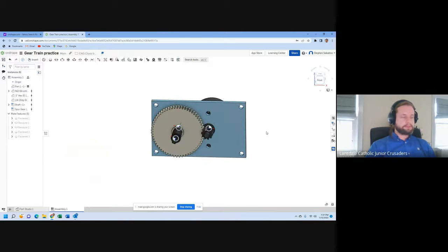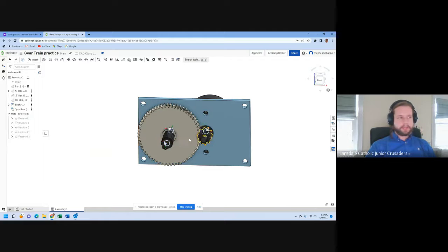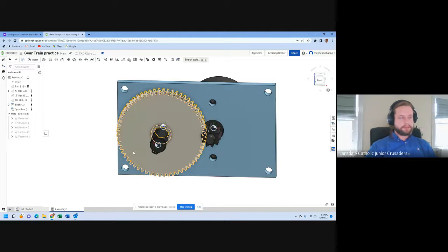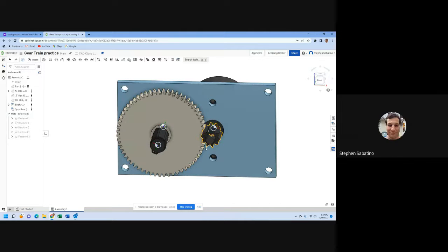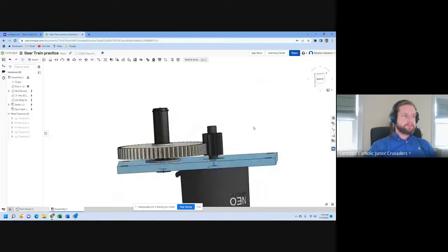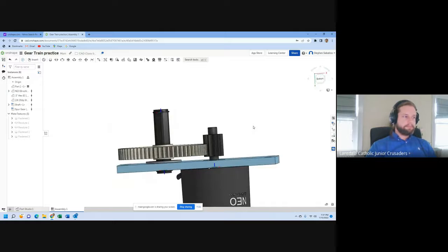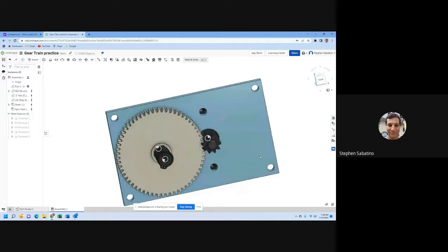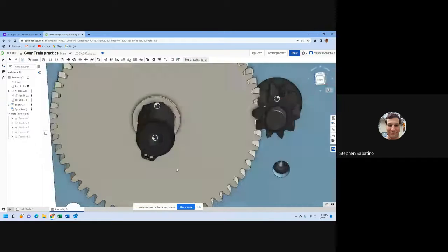Okay. So again, there are instances where you will need offsets for certain things, but none of the stuff that we've done so far really necessitates offsets. The only place where I did do an offset is on the spur gear, and that one kind of made sense to me. Normally you don't want to have those gears all the way up against the bearing for obvious reasons. The gear will grind against that bearing. So that's one of the places where you don't want that. And then my hex shaft is not aligned, so I made that wrong too.